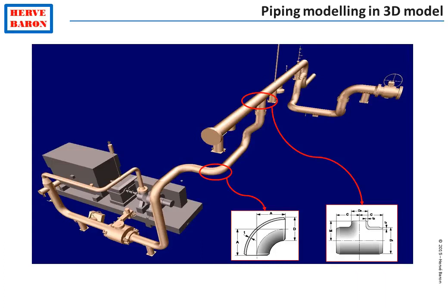However, some items are not standardized, and these include control valves, as well as inline instruments and pressure safety relief valves. So for these items, the dimensions must be provided by the vendor and must be input in the system.